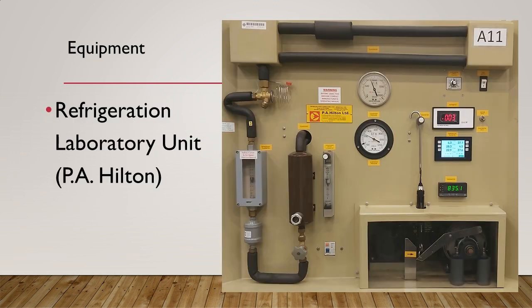The equipment to be used for carrying out this experiment is the refrigeration laboratory unit manufactured by P.A. Hilton. It consists of a twin-cylinder compressor driven by an AC motor through belt and pulleys, a water-cooled refrigerant condenser, a thermostatic expansion valve and evaporator.